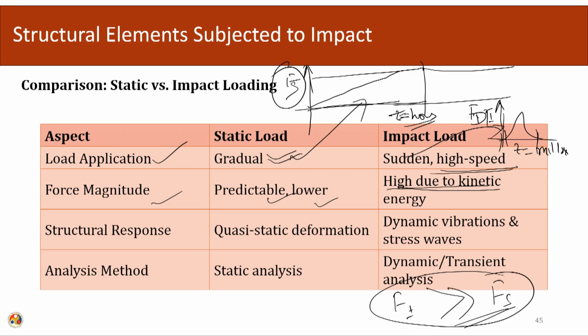Structural response. So, structural response in what is known as the quasi-static deformation, and in this particular case of the impact loading, the structure is going to vibrate, and the stress is going to occur. So, here what is going to happen is that the structure will start to vibrate, but since the loading is applied gradually and it has a low magnitude, the transients will die down. So, only the steady state with a less magnitude. Let us say this is the deformation. So, then this will be proportional to f over k.